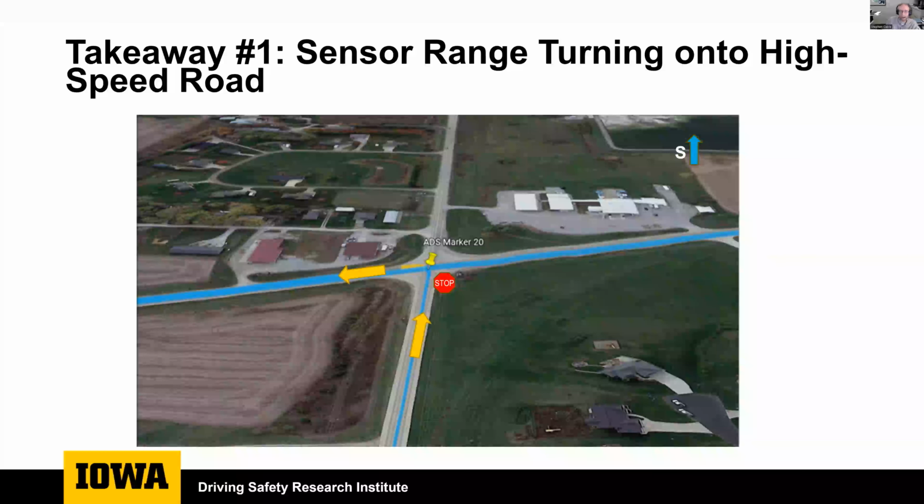And then complicating all of this, the turn wasn't a clean perpendicular turn. We were making a turn that was about 110 degrees off of the heading, which made it an awkward angle for that fused LiDAR point cloud to see obstacles coming from the left-hand side. And so in practice, there were quite a few times where the vehicle had to be taken out of automation to safely make this turn manually.